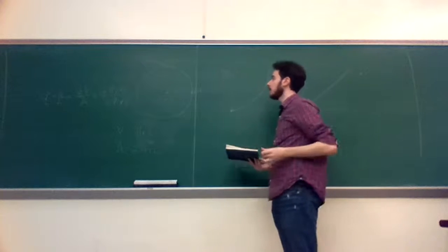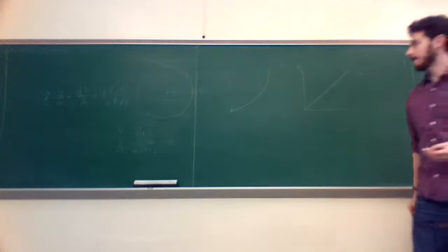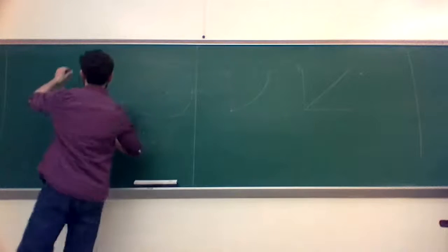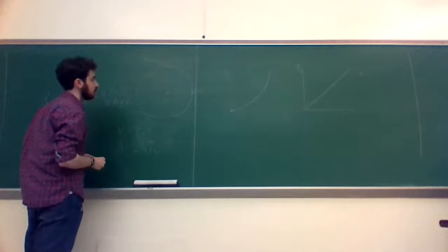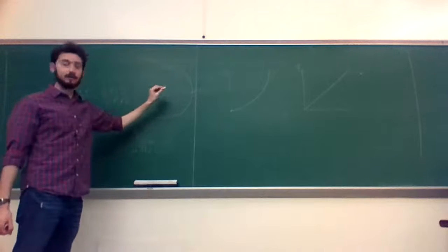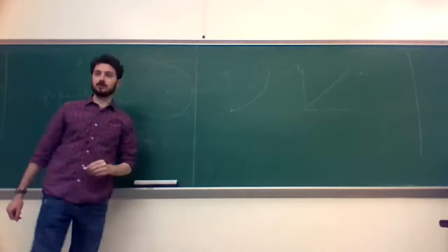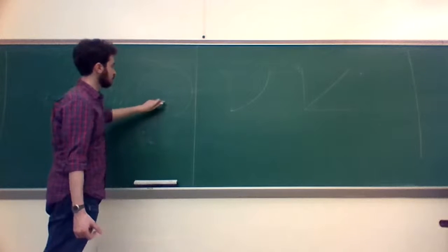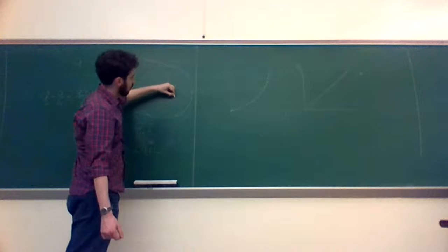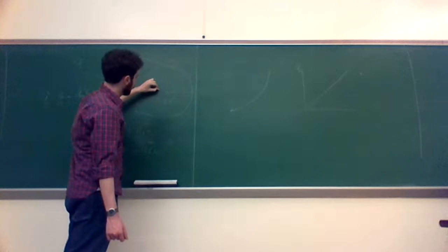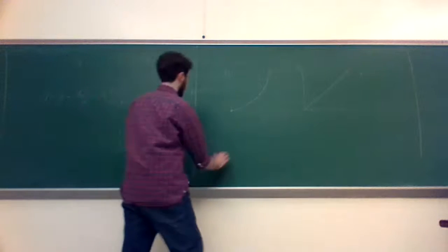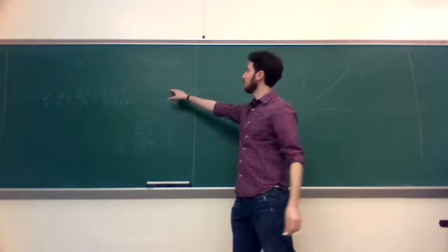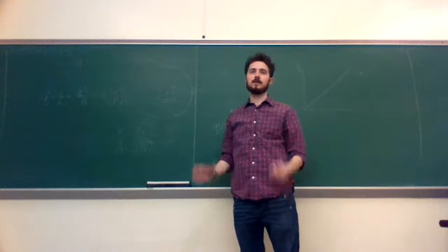So starting with heat rate, as you move further out, you're capturing more and more volume of the cylinder. And your Q, at any point, actually we'll just start with an arbitrary slice, right? An arbitrary cylindrical control surface. So it looks just like the cylinder, centered at the origin, but somewhere between the origin and the outside of the cylinder. Your total heat rate through this cylinder, Q at r, has to be exactly equal to all of the energy that is generated inside that control surface.